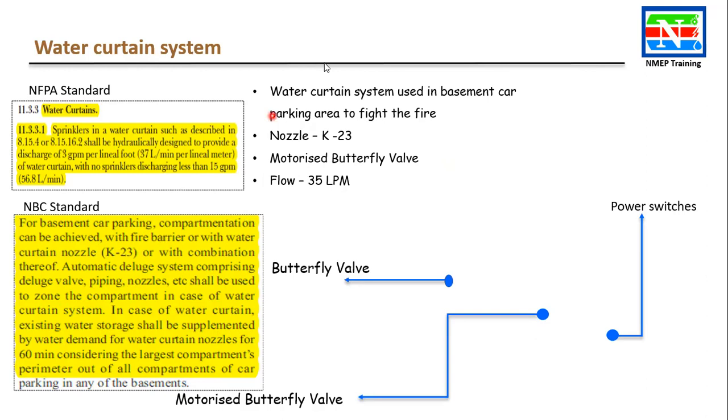Approximately how much tank is required, that we will calculate. I'll give a brief idea. How we calculated for 30 minutes, 60 minutes, right? Based on the LPM. Similarly, you can calculate here. But that is for one sprinkler, and we have multiple nozzles, right? Yes.